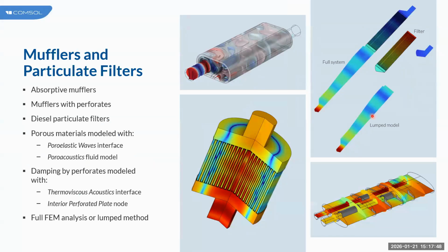So moving on, you can also simulate mufflers and particulate filters by coupling acoustics with fluid dynamics and structural mechanics, analyzing phenomena like pressure wave propagation. You can analyze the acoustic damping in your porous material, or study the shell vibration that is going to affect the noise reduction mechanisms that you're going to take to improve your design.